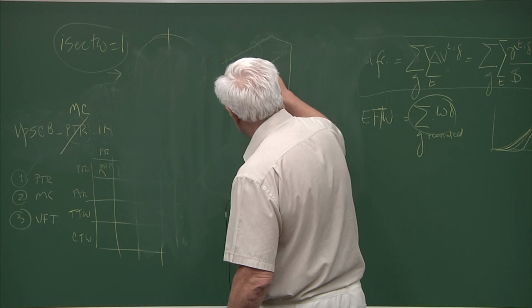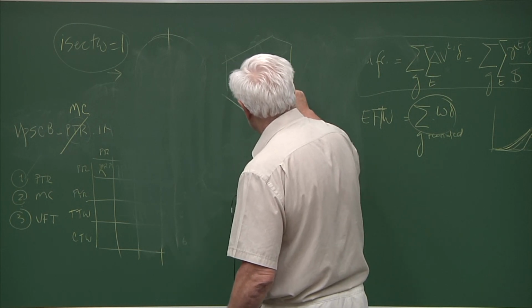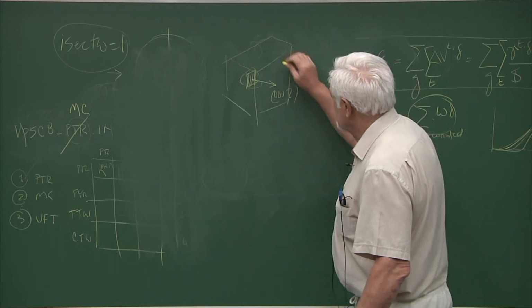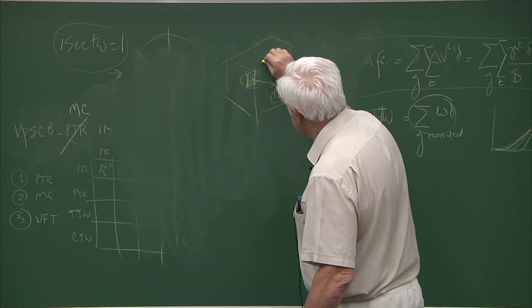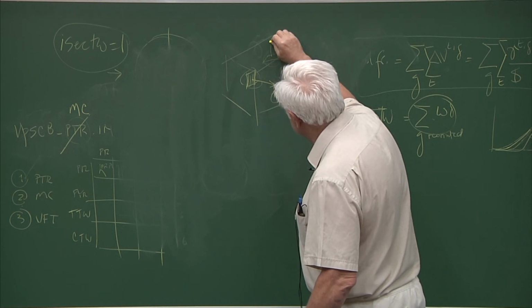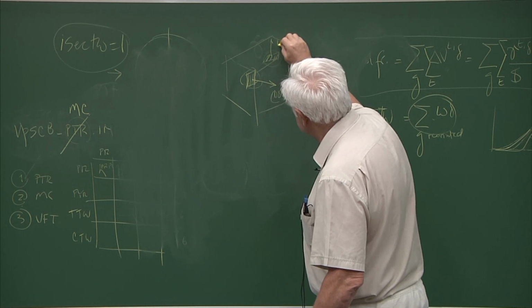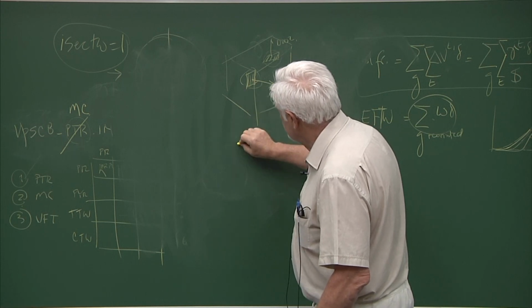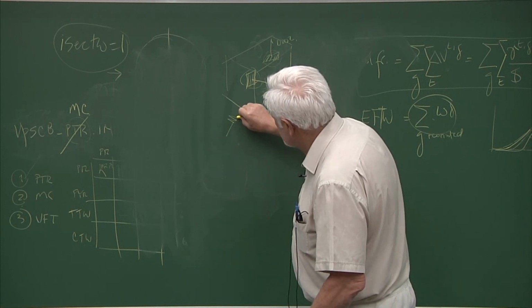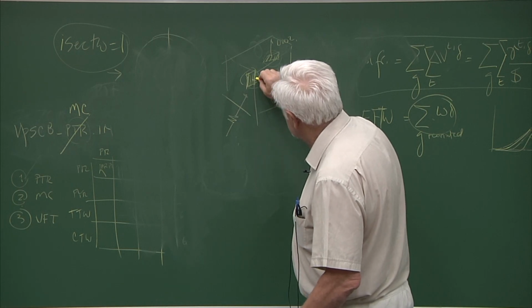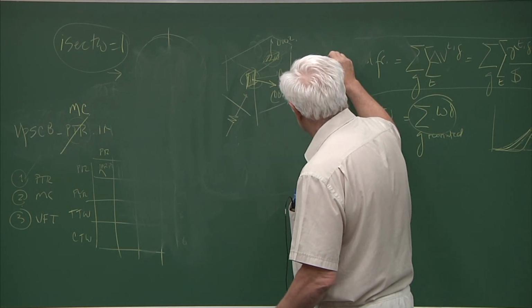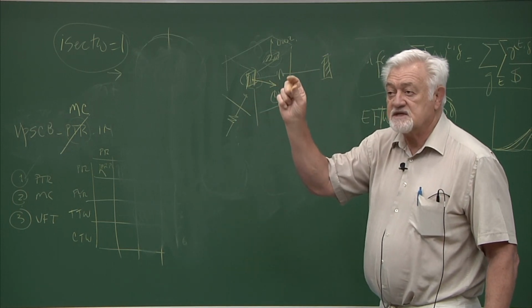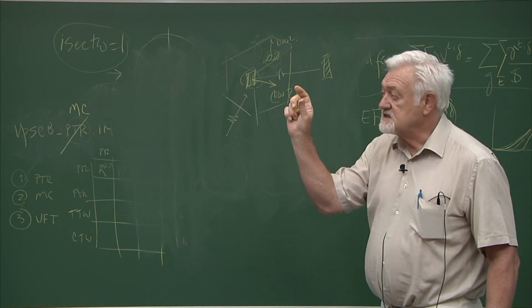Let's say this is your basal plane. There are going to be other grains that maybe have basal planes oriented in other directions, like this. If you throw X-rays into this plane, it will diffract them into a detector. And you capture the change in lattice spacing associated with the fact that there is an elastic strain.